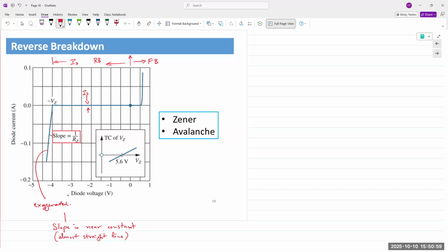So you're applying a reverse bias. That reverse bias is an external electric field. When you apply a high electric field density across a very small region, it imparts sufficient energy to some of the charge carriers that they break free of their bonds and are now available for conduction.